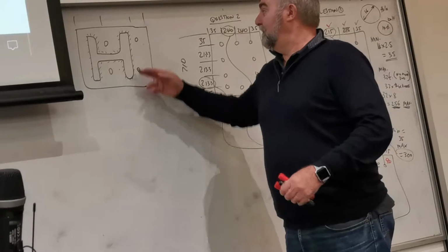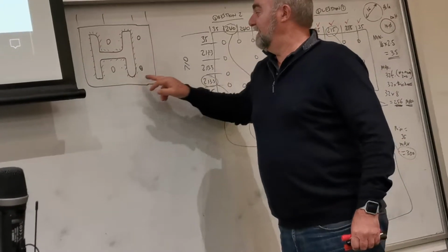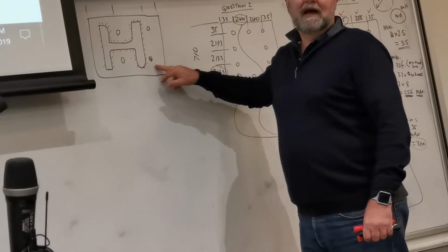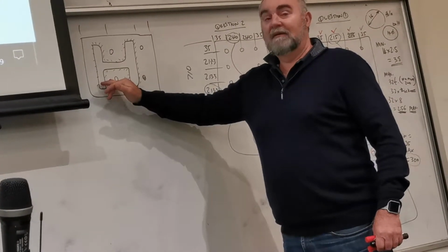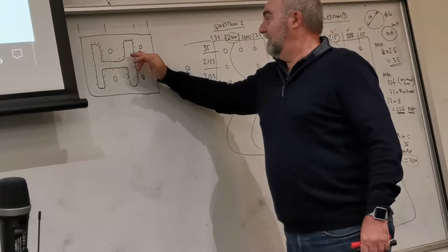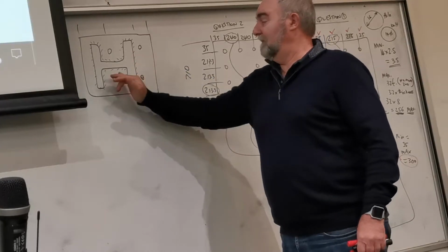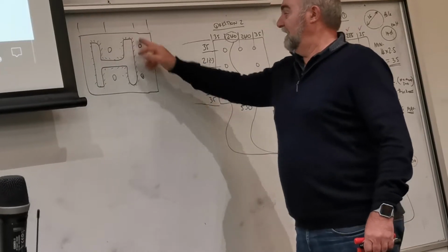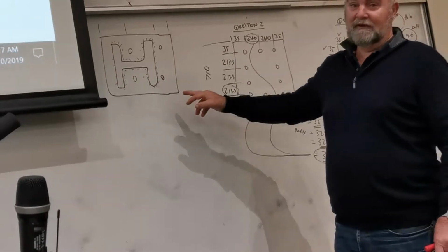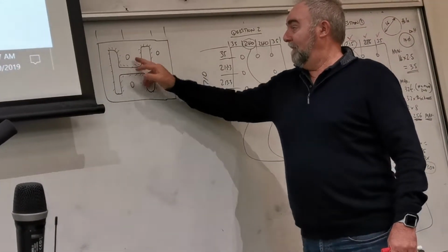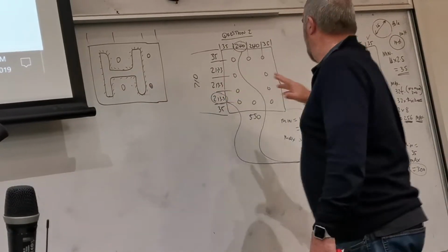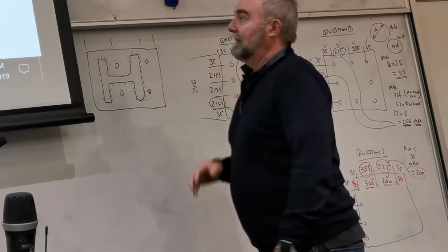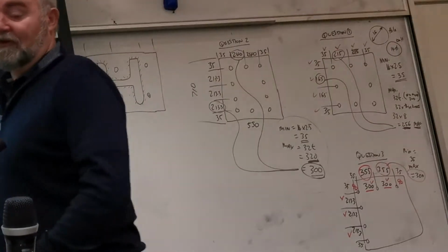So if it's impossible to put the bolt holes in the corner, then bring it in to where the first position is here, and then where the first position is that you can fit them in this side. Some students have only done 350 by 350, so they're going to struggle. They may be able to put the bolts in there, I'm not sure. Okay, so that's plate design.